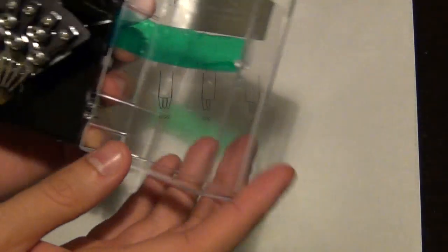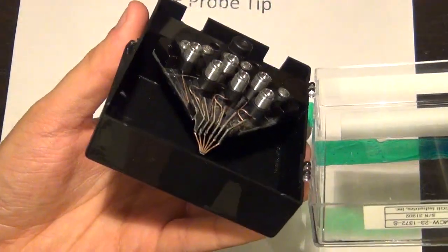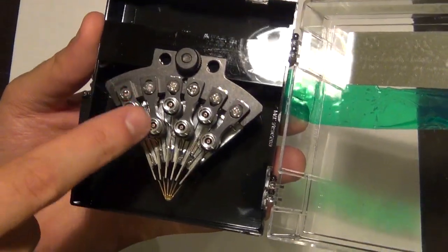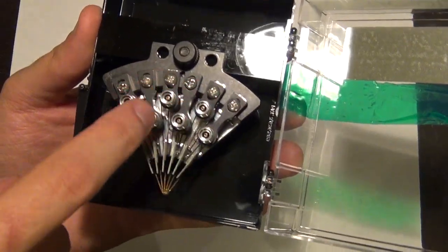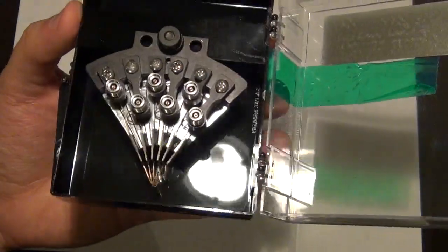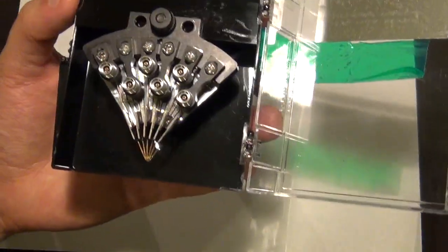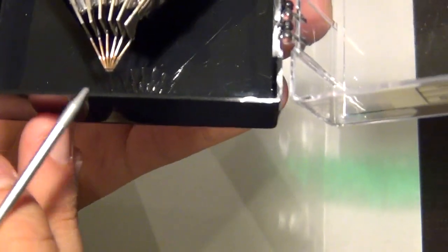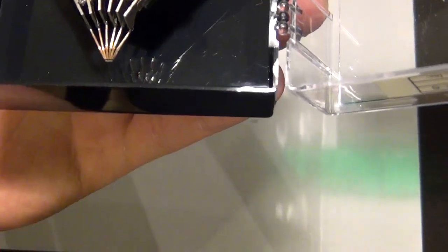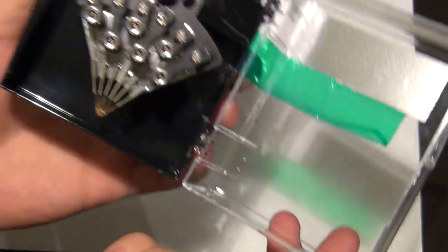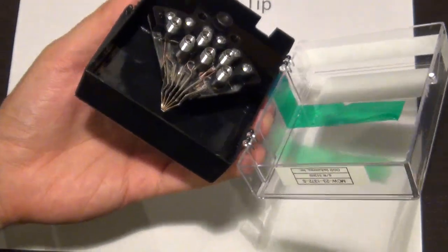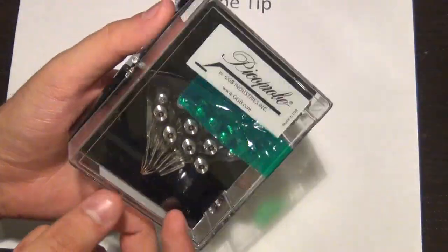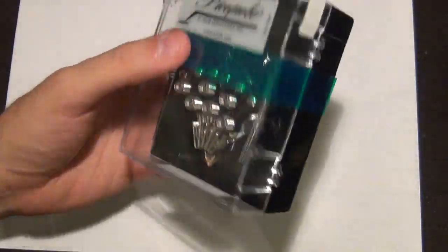This one is from another company called GGB. This is a completely custom made probe. It has many K connectors, so it has 1, 2, 3, 4, 5, 6 40 gigahertz connectors on it, and all of those wires end up at the tip here. So there are many wires here that land directly on the circuit. This is also 100 micrometer pitch. Very expensive because it's custom made, but GGB makes these things depending on the configuration that you want.